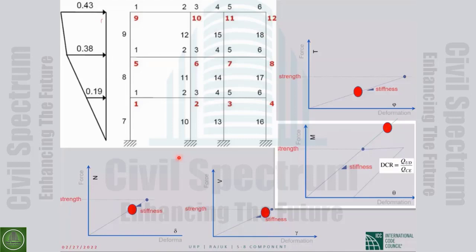Based on the response spectrum and the weight of the building, we calculate the base shear. We adjust the base shear to give us the same displacement as reality with C1, C2 times Cm. Then we look at the responses. We do some adjustment in the responses, full adjustment for the force control responses, and check with the lower bound.